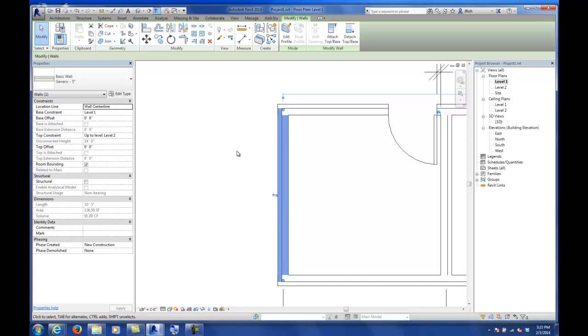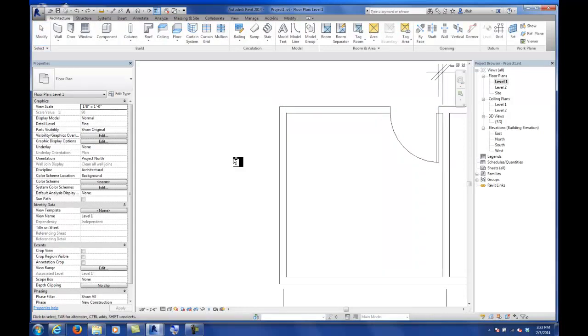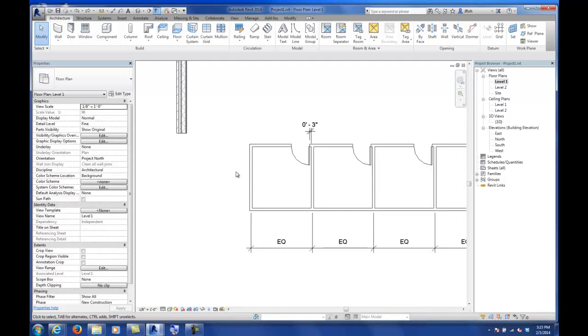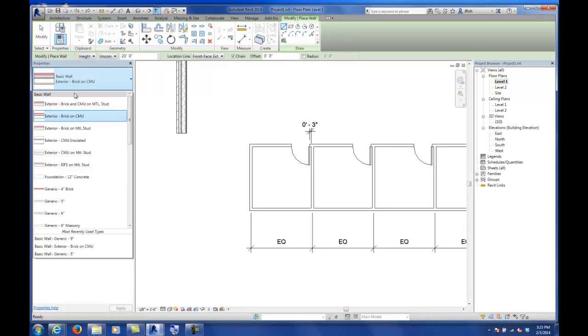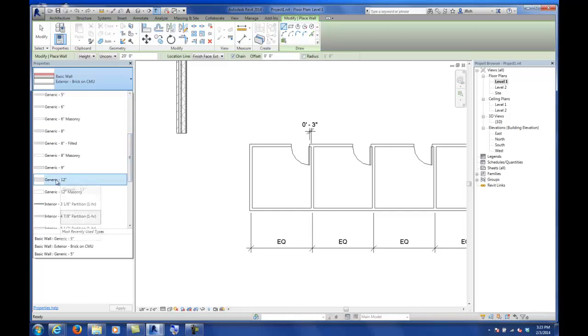So I'm not going to hit on the compound wall idea so much, but what I want to do is talk about stacked walls. You can see right now we've drawn just that one wall type, but we can actually stack walls on top of one another. As long as you have a wall type made, so let's say I go back to my walls over here under architecture, and I've got a 5-inch wall that we've been working with,